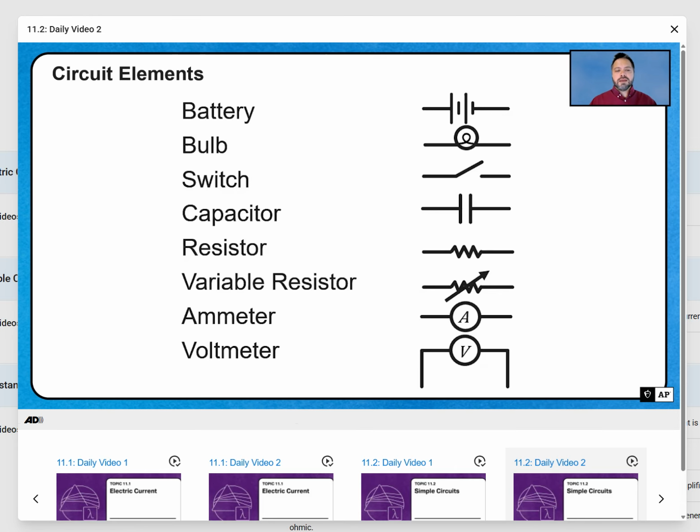And what we mean by that is as you move the dimmer switch up or down, or dial in a different setting, what you're doing is you're moving the two connections. So on the brightest setting, the connections may be so close to each other that you're not really going through the resistor. And then as you dim your light, you're moving the second connection further along the resistor, so the charges have to flow through more of the resistor.